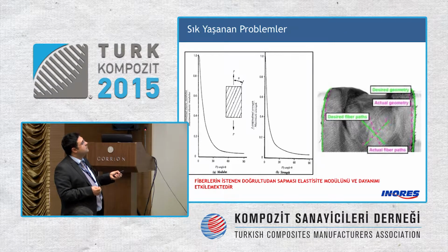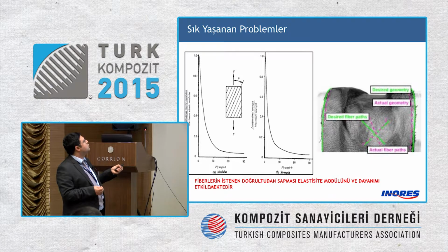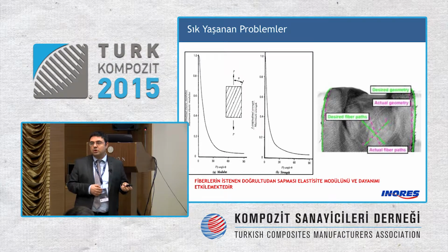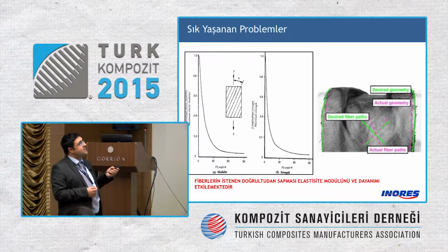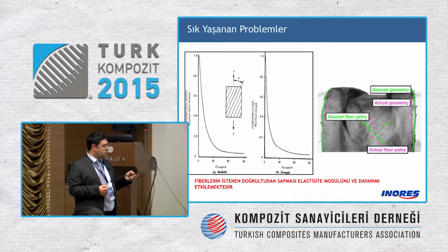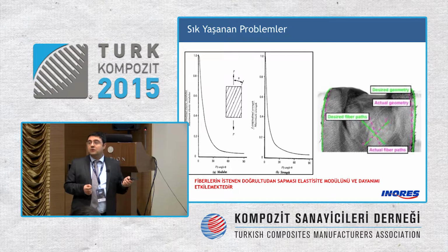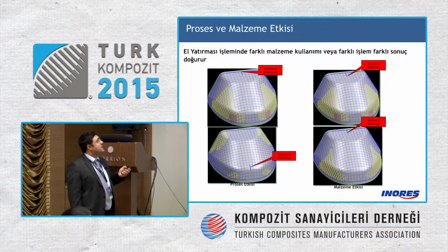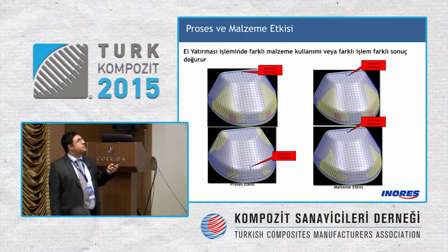Here on this graphic, for instance, the fiber orientation angle is on the bottom side and the linear line is about the elasticity ratio. Even with 10 degrees of difference, there is a high loss of strength or endurance. Therefore, lots of issues have to be pre-assessed before design and production.